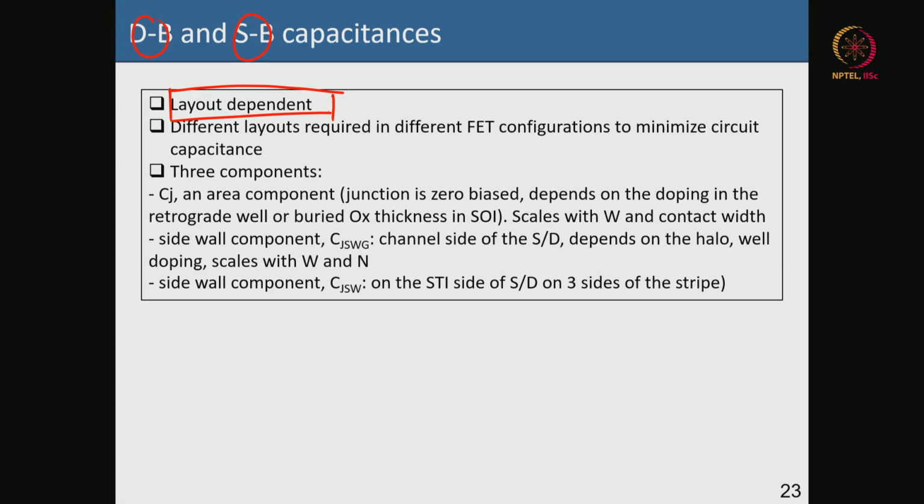When I say layout, how many fingers are you giving? Are you contacting the gate from both sides? How many vias are you giving on each finger stripe, or drain or source stripe? The overall device geometry is very important. Okay.